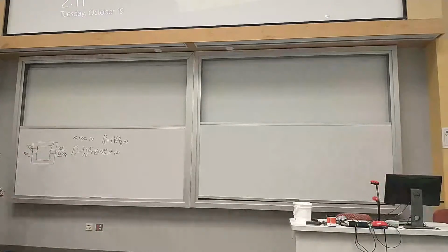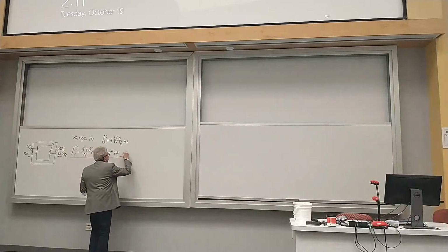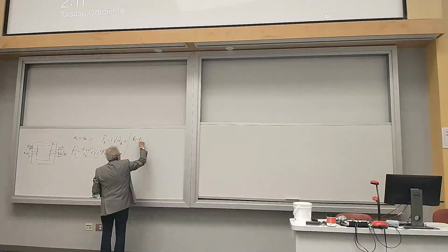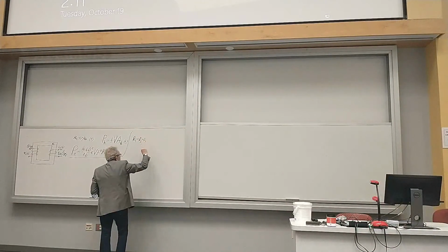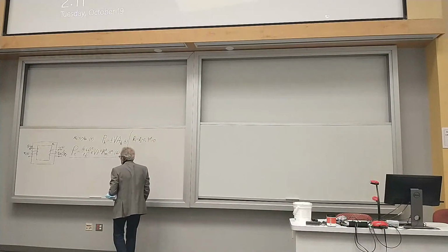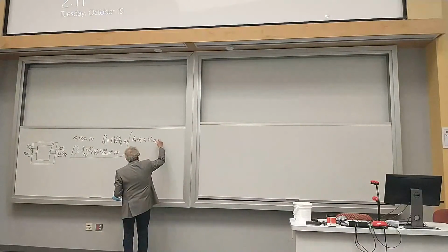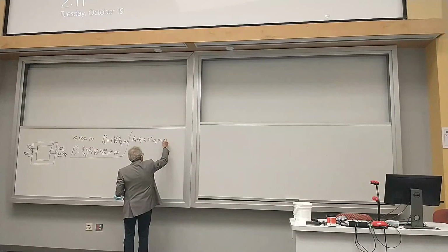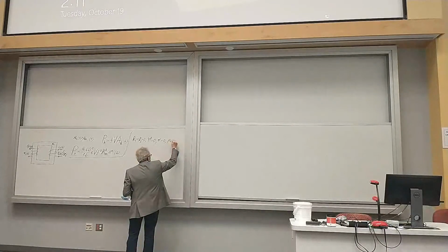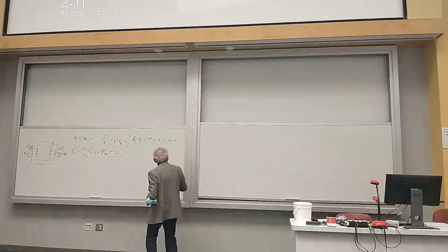And what I did first, I considered the so-called ideal transformer. In the case of the ideal transformer, we use the following assumptions. We neglect the resistance of primary and secondary winding. We assume that it's equal to 0. We neglect the leakage flux. We assume that all magnetic field lines are confined to the ferromagnetic core. We neglect the conductivity. In this way, we assume that there are no eddy current losses. We neglect hysteresis. We assume that the core can be characterized by magnetic permeability, which is very high and often assumed to be equal to infinity in some calculations.